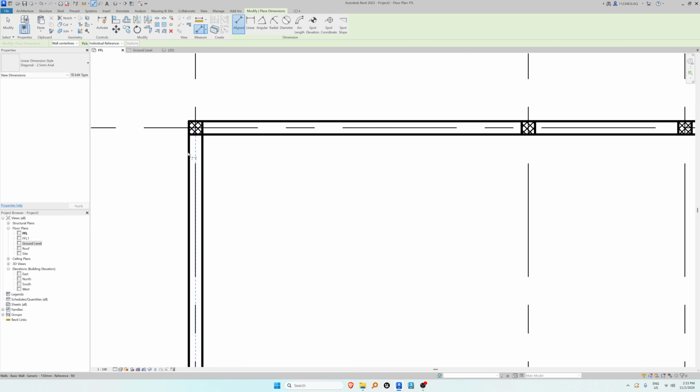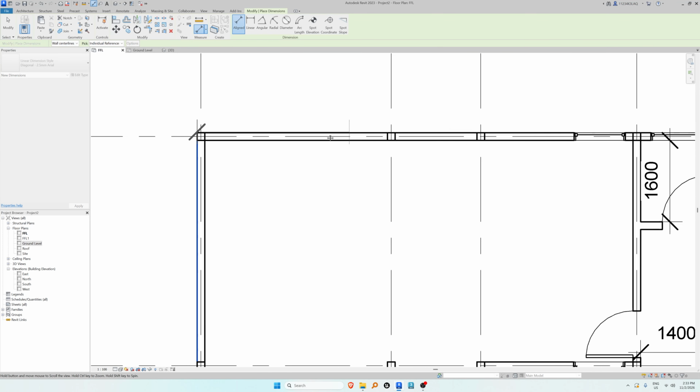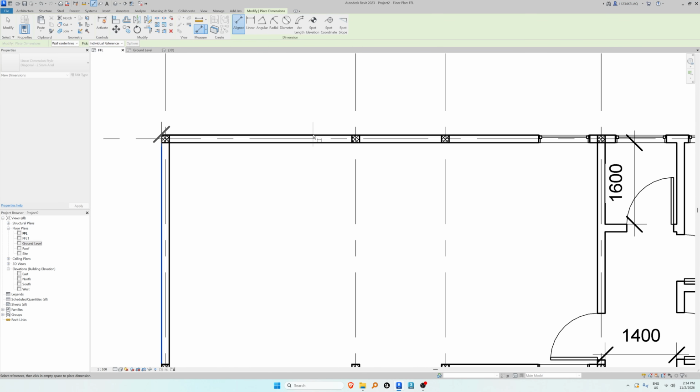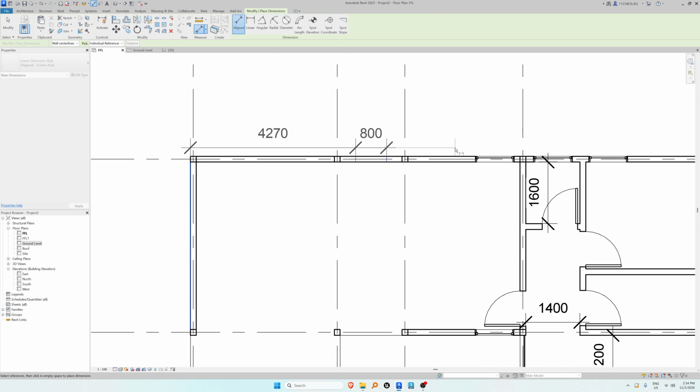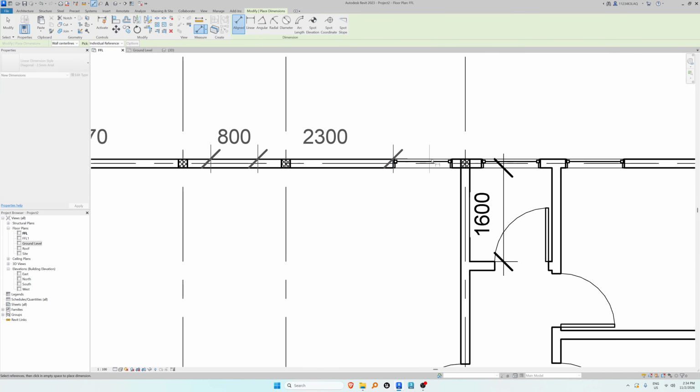Right, so you pick the edge, tab. Remember, if you cannot pick the face, you tab like we did for massing. And then you want to find that window, which is somewhere here to here. So yeah, make sure you find your window. So here, right, and then you have this window.